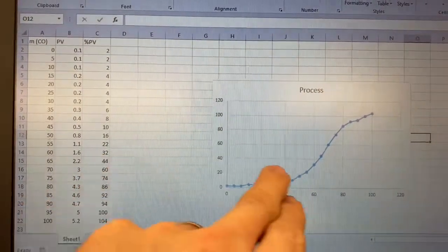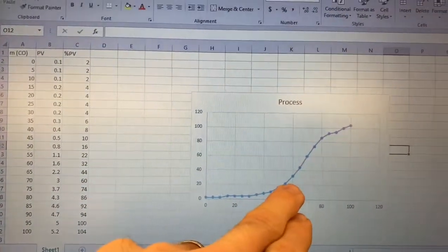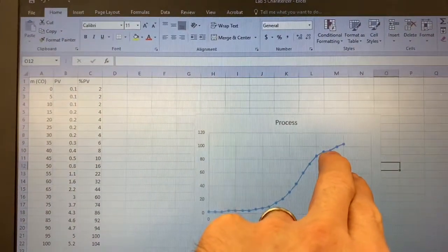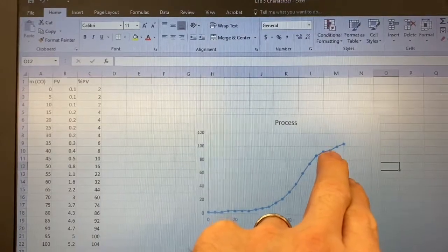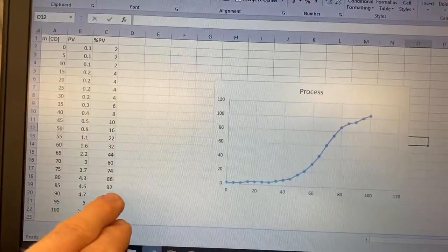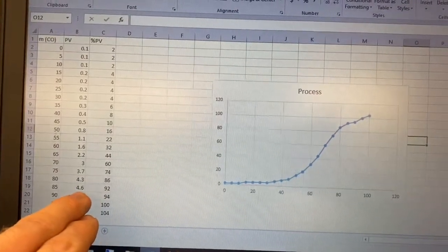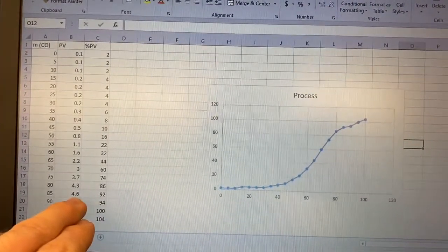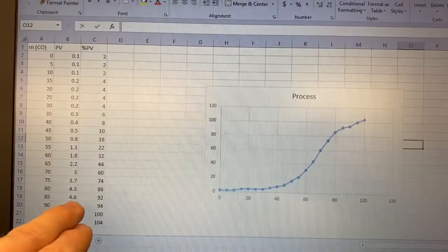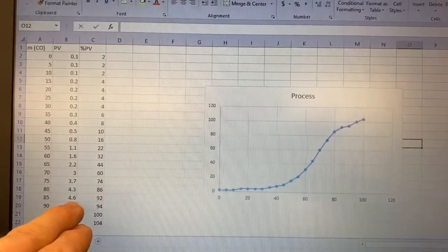So yeah, we use 1. And then it looks like maybe we can taper off and use those higher gain values again once we get to about 90%, which would be around 4.6 psi. Sure, we'll use 1.1 and 4.6 for our values.